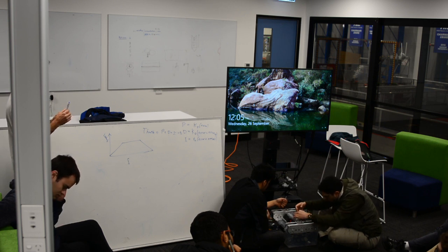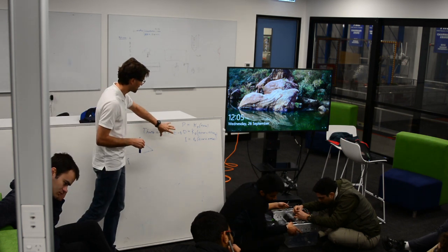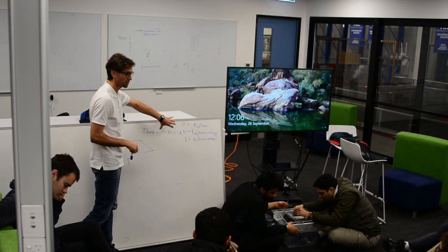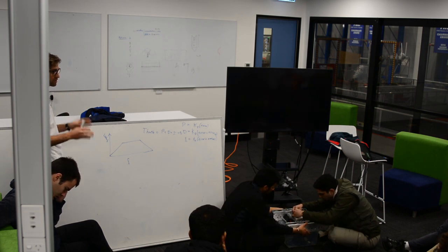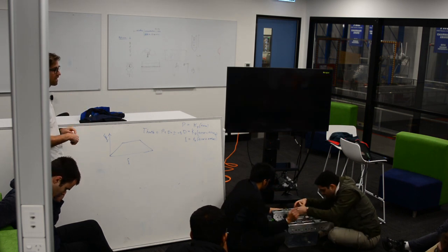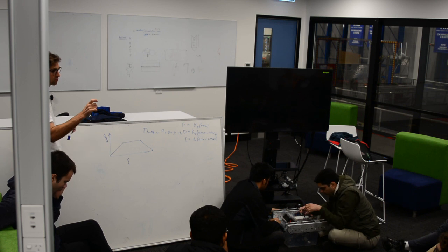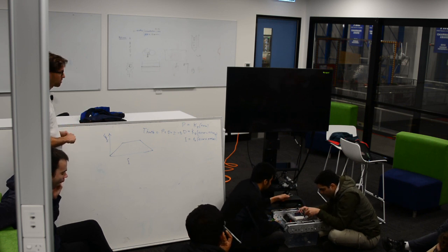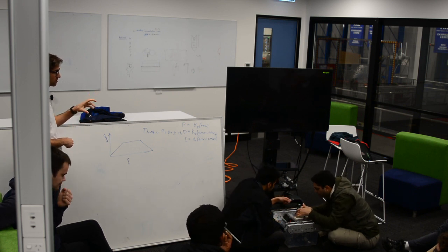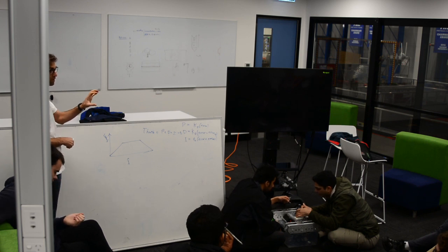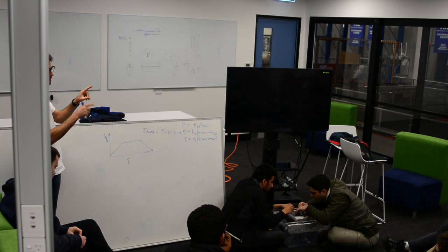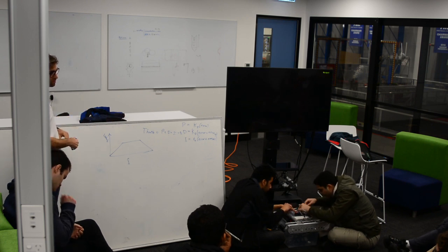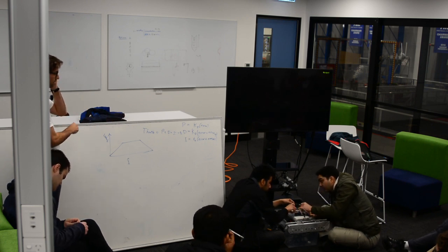Or what about changing the gain? Normally the way that it would be done is you would leave this as a tight control system that always keeps the system in position. That's its sole job, is keep it in position, in position, in position, and momentarily be out of position as you're moving it. But you might have a move function that will take position commands, and its job is just to keep it in position. That's how I would do it.